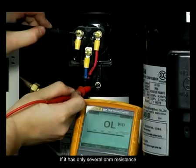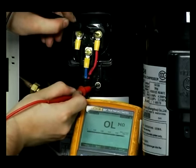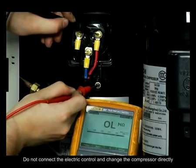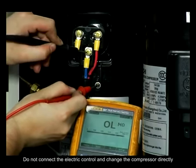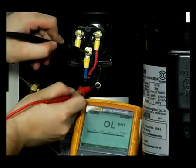If it has only several ohm resistance, that means the compressor has been short-circuited and damaged. Do not connect the electrical control and change the compressor directly. If it is normal, please go to the next step.